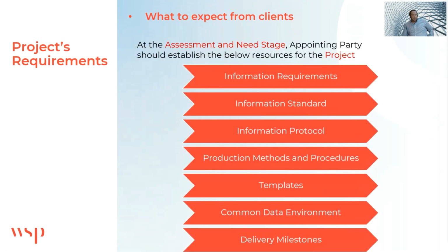So back to the practical approach. We spoke about the standards, and how this can be translated into something that can be added into the EIR. So when you look into an EIR, or when you ask the client for the EIR or the PIR, what is actually expected from the client? As per ISO 19650, the client has two important points in the project lifecycle where they should provide the information requirements.